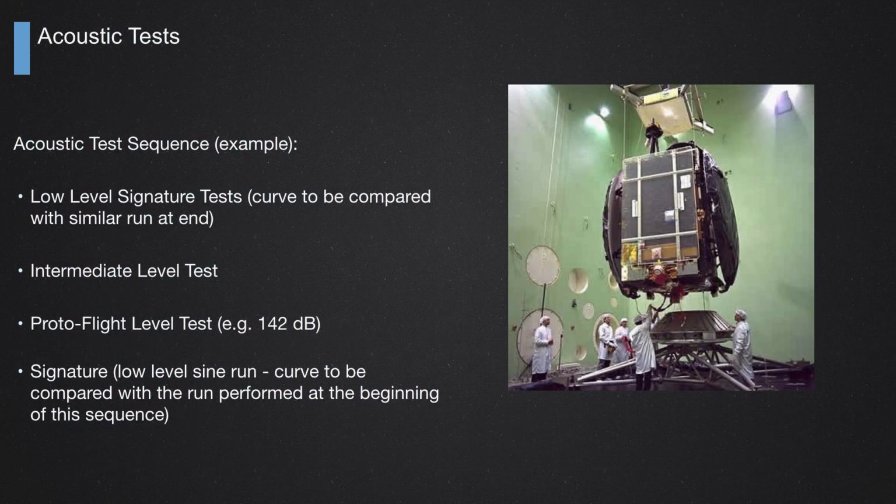So then we measure this with microphones. We can install, let's say, 8 or 10 microphones around the spacecraft to ensure the level of acoustic waves arriving at the spacecraft is as expected. And the 200 sensors are used to analyze the response of the spacecraft, how the spacecraft is going to vibrate after the input of the acoustic waves. Okay? As I said, we program the horns with the curve of the launch vehicle plus the margin.